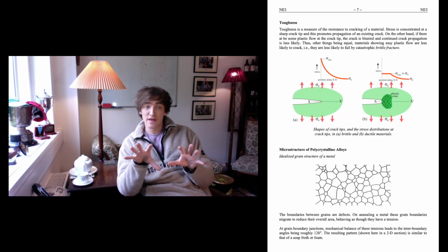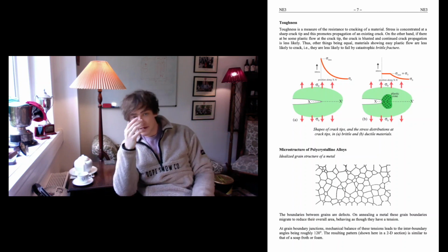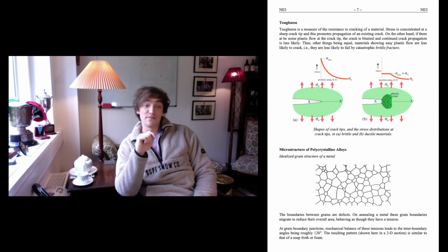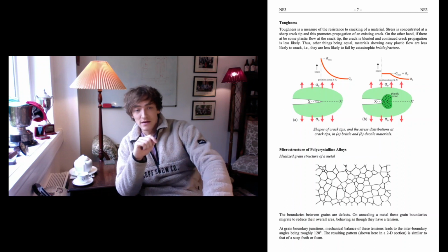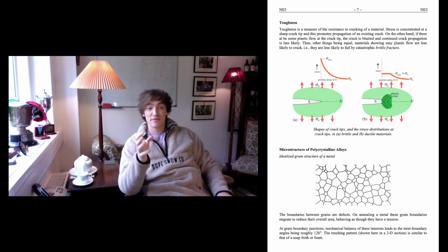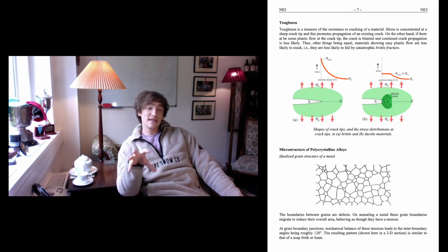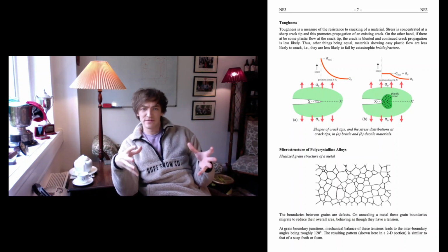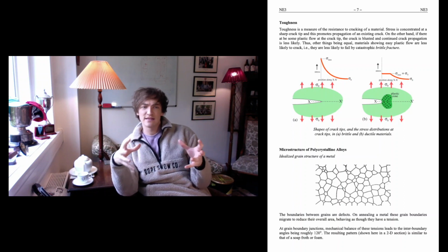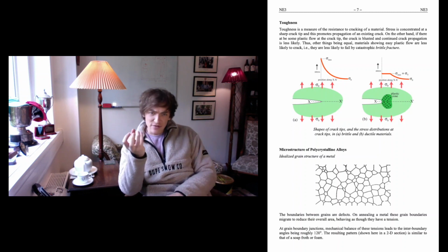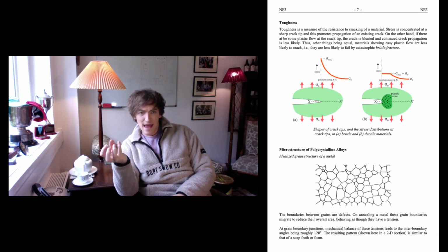I strongly suggest you go back over this in your own time, like I do for all my lectures, but here it's especially important if you haven't done material science before, because now we're going to move on to microstructures. Because most materials we'll look at in the nuclear materials course are polycrystalline, and that means that they're made up of multiple crystals. And crystals are an ordered lattice of atoms in a tessellating, repeating pattern. And these crystals are called grains. And between each grain are grain boundaries.